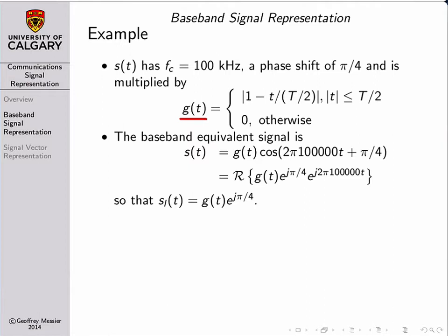Normally a communications passband signal contains an amplitude and a phase term that are constantly changing, right, as we use that wave to transmit different information bits over a certain period of time. And usually what we do is we model the variation in the amplitude and phase as random, and dealing with those random variations is something we're going to be talking a lot about later on in these video modules.